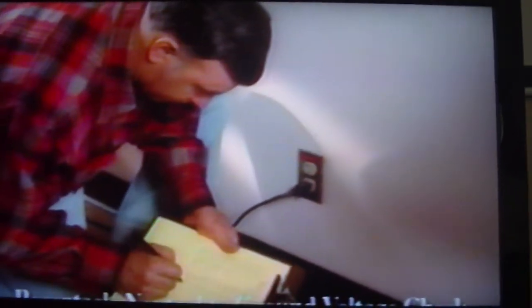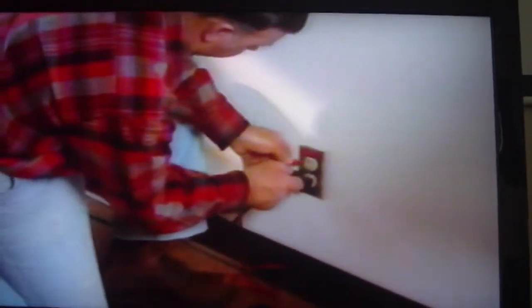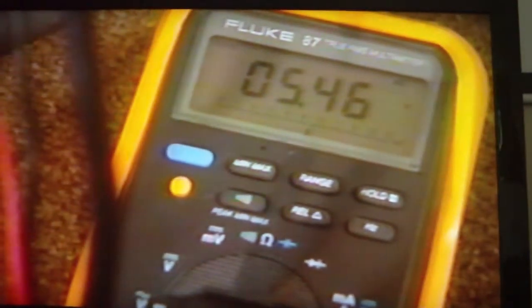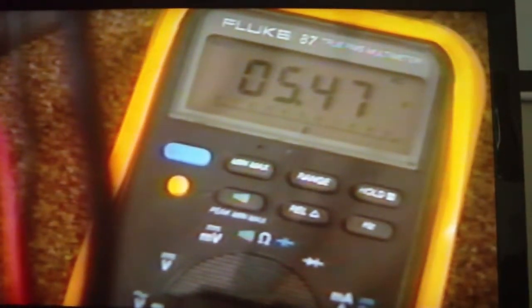To detect overloading in receptacle branch circuits, measure the neutral to ground voltage when the loads are on. 2 volts or less is probably normal. Higher voltages can indicate trouble depending on the length of the run and the quality of connections. Once you've followed these steps to locate where harmonics are occurring, you can begin to solve the problem.